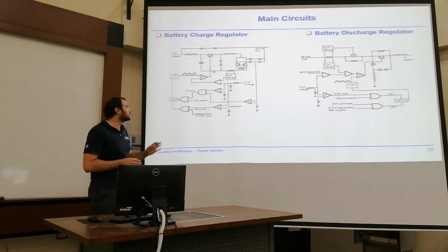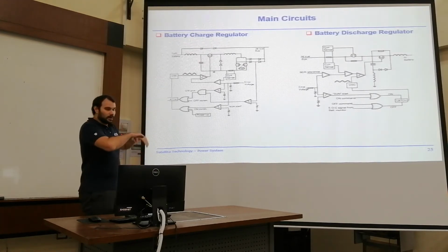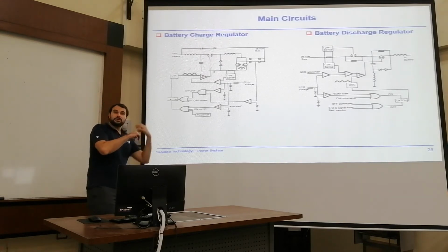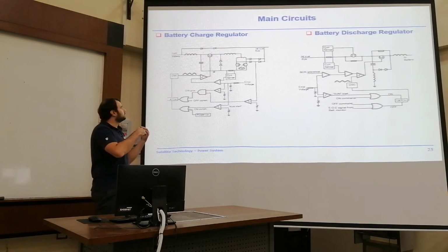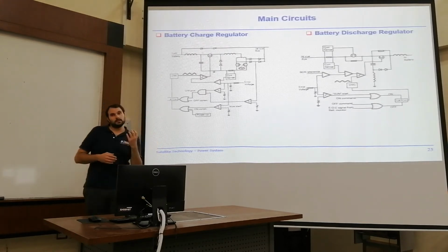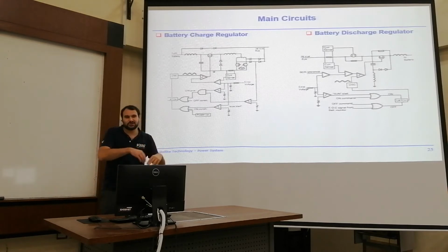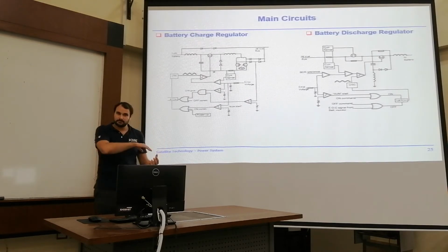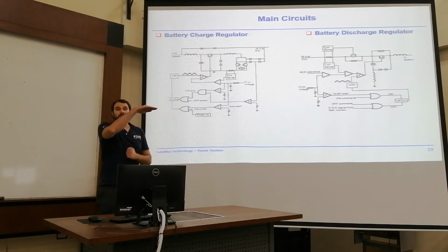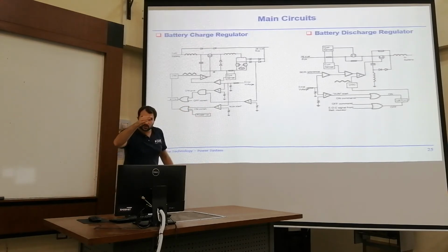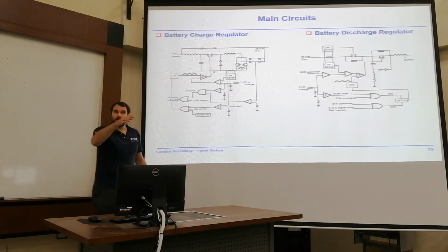Unfortunately I don't have a pen here, but it doesn't matter. By dynamically switching your switch on and off, let me approach it that way: the moment you close the switch, you charge your coil, and the current goes up. Then you try to discharge your coil, so all the output is being fed by the coil, and it decays. But instead of letting it decay to zero, you switch it back on and recharge.